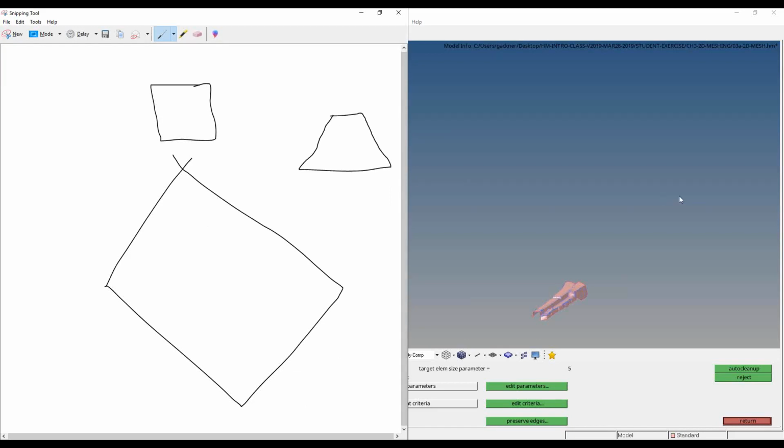Inherently, at this point in time, with 2020 software, HyperMesh and OptiStruct are smart enough to know to do slightly different math on all of these slightly different shapes and can account for the individual element deformation. So the reality is the solvers are so good that individual element quality isn't as important as it was once upon a time. And Darius, certainly tell me I'm wrong if I'm wrong in that case.